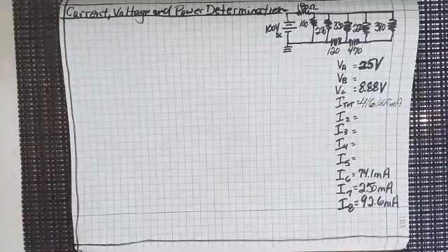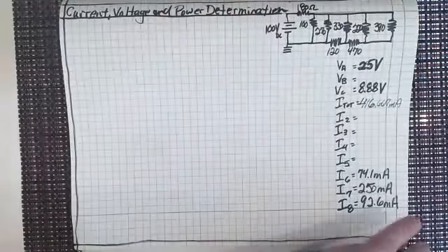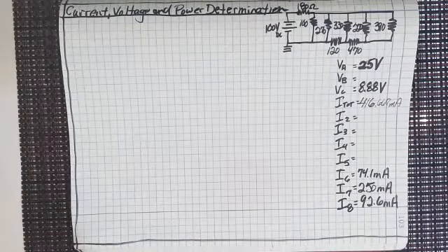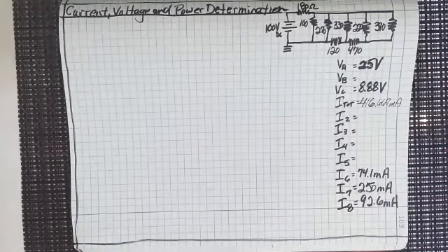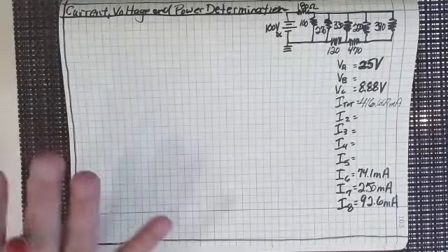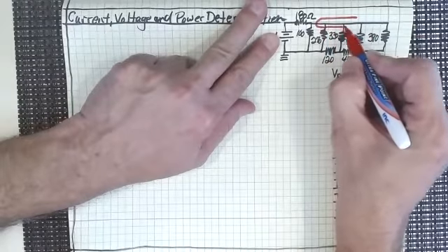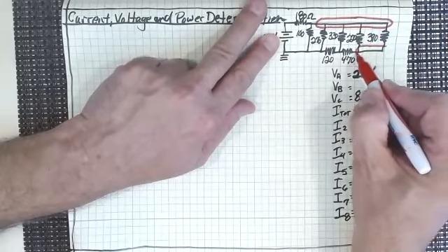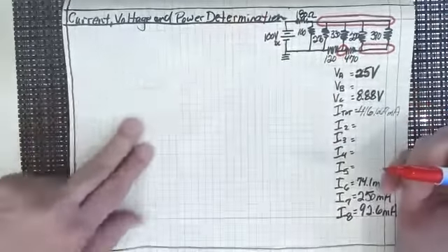What we're doing here is something that all electrical engineers have to do when they're learning the fundamentals of network theory 1: they've got to hone their skills at series, parallel, figuring out where nodes are, learning how to expand out a schematic from what you find on a printed circuit board, which is what we did with this, looking at the 3 nodes, applying Kirchhoff's current laws.